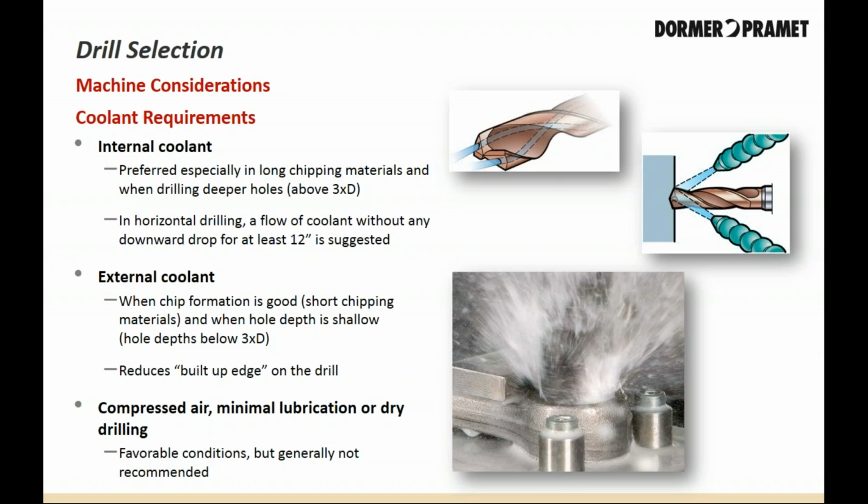Through the tool coolant or through spindle coolant is always your best choice when possible, especially when using solid carbide drills. Coolant through the tool is almost always best, except when drilling extremely hard materials. In these cases, sometimes a solid tool can be a better choice, as material removed from the tool for coolant holes can weaken the cross-section of the tool and cause breakage.